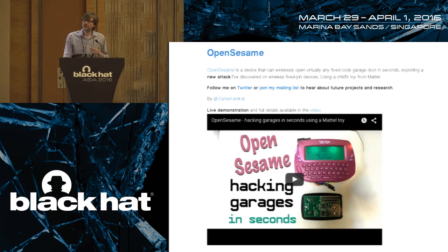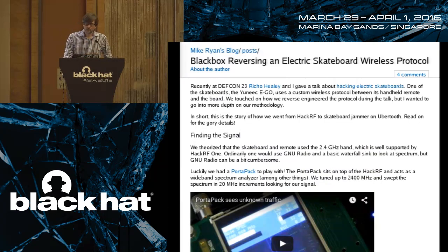But as he was reverse engineering remote keyless entry systems for this research, the approach that he used was exactly what I'm showing you today. He used SDR as his initial recon to figure out what radios were doing approximately, and then learn the physical layer characteristics. And then once he acquired those physical layer characteristics, then he turned to Yardstick 1, just like I'm going to do today. And he used Yardstick 1, and also some other wireless transceiver IC platforms, to implement the attacks.